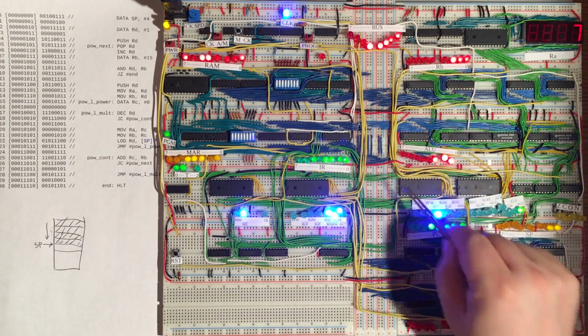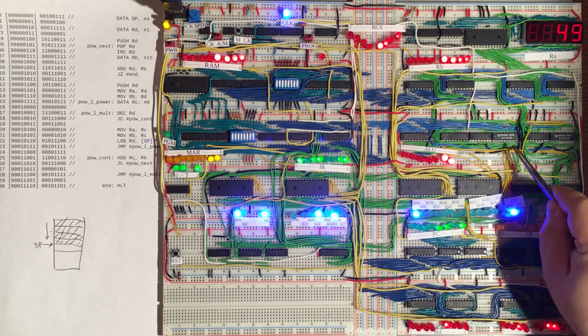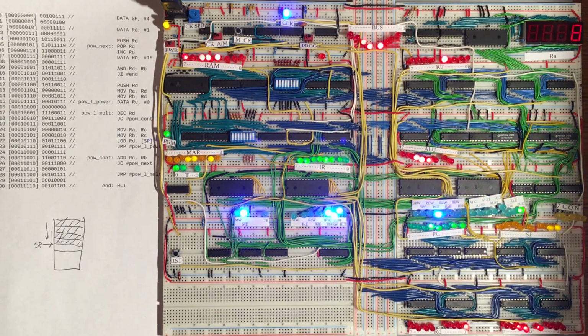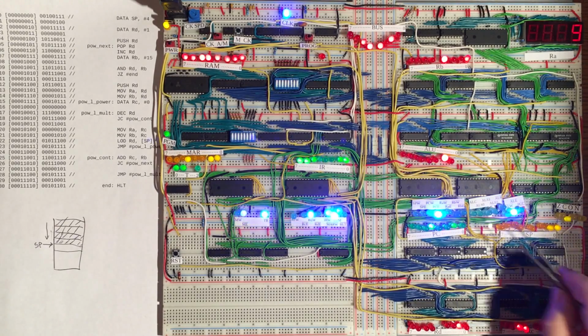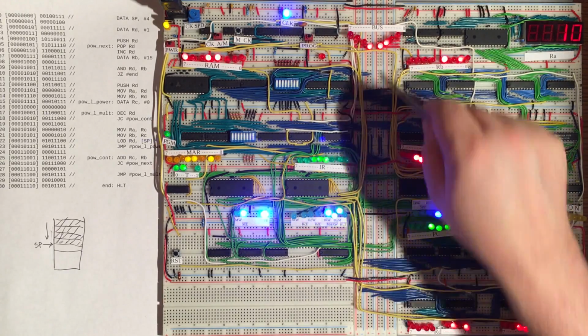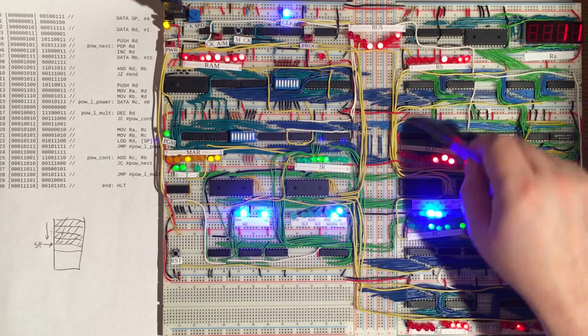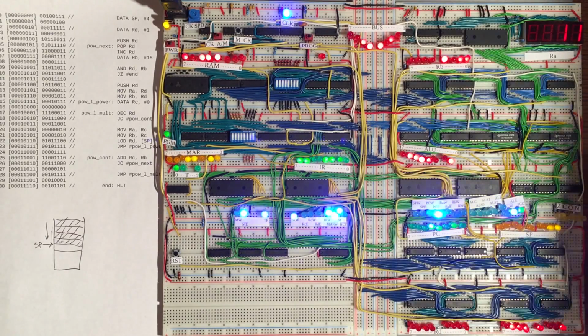We had a look at the ALU and how we're using these 74LS382 chips to perform the various operations which we support. We looked at how that produces flags, outputs, and also numerical outputs, of course, and we use the bus to transfer that to and from the various registers in our computer.